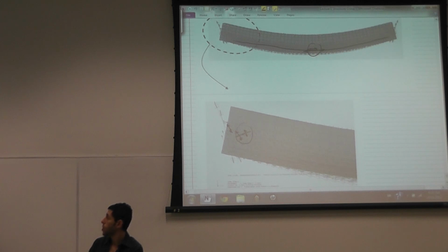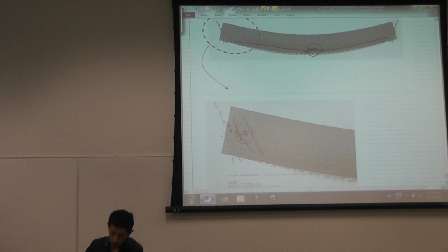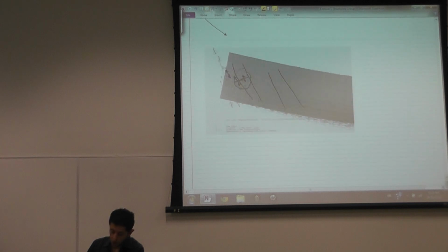And that's why you need what we call the shear studs, or shear reinforcement. And in the past, when I studied concrete beams, we used to put the shear studs or the shear reinforcement in this direction. But I think now it's easier for manufacturing and for everything that the shear studs are more oriented in this direction. It's easier for manufacturing.